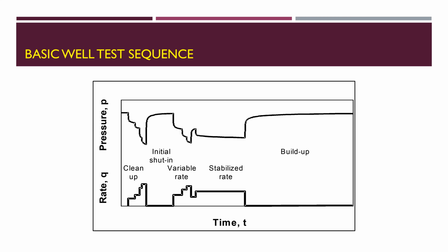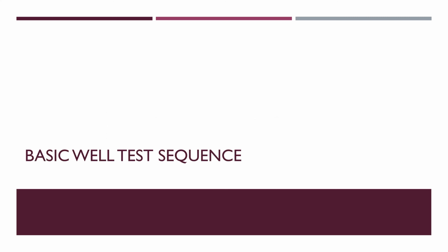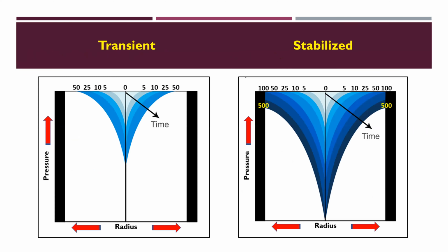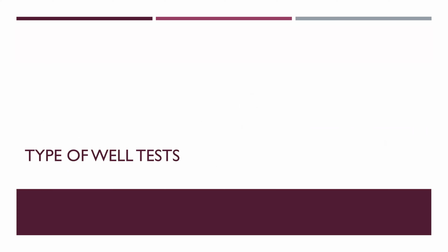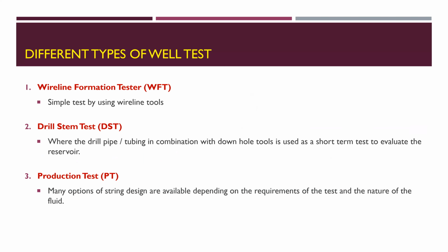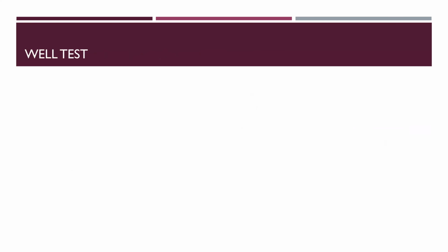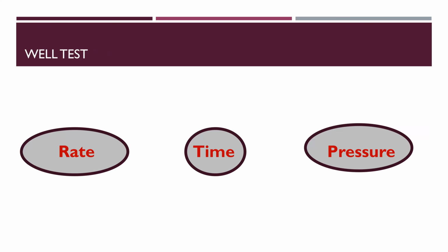First of all, remember that we need to see the report that used to come with the test data in terms of time. I need to be sure that I have an interpretation or justification, a real meaning, for any anomalies we have in pressure, because I need to distinguish if the noise in the pressure is coming from something related to the reservoir or from something that happened at surface or in the wellbore.